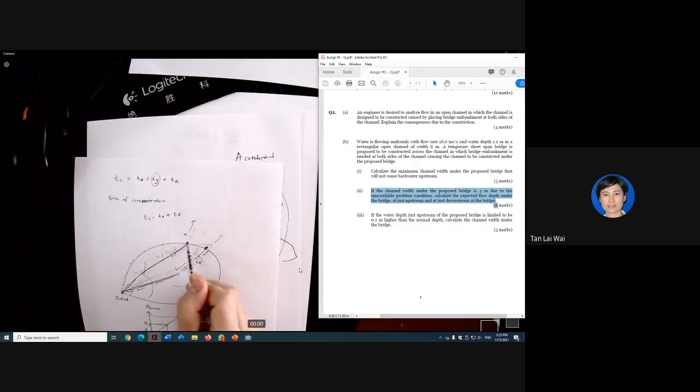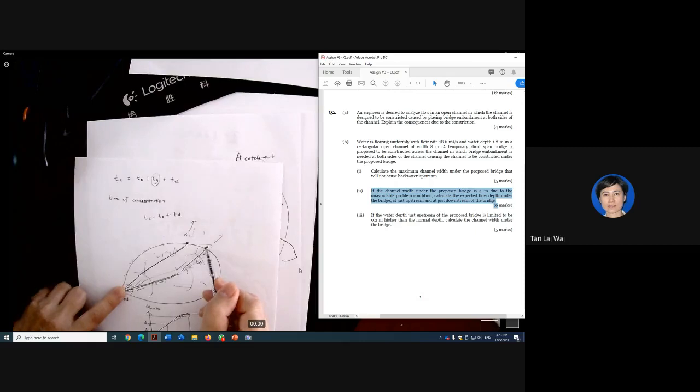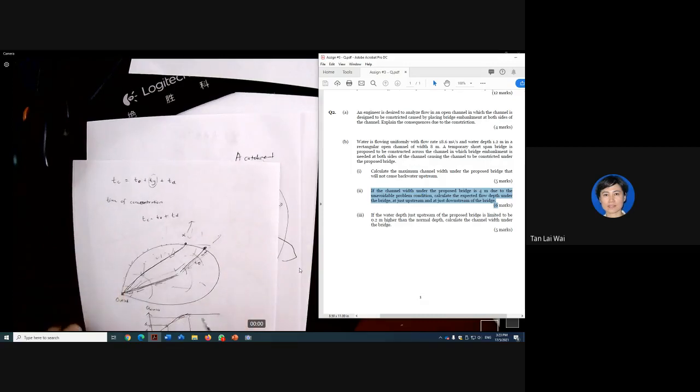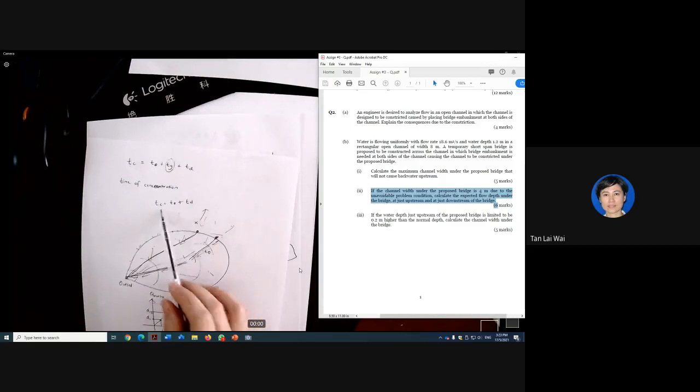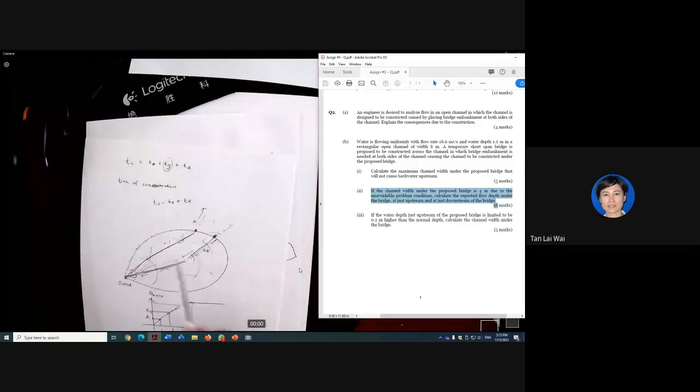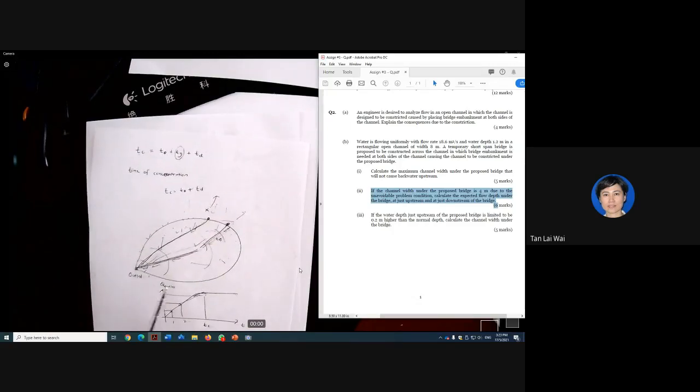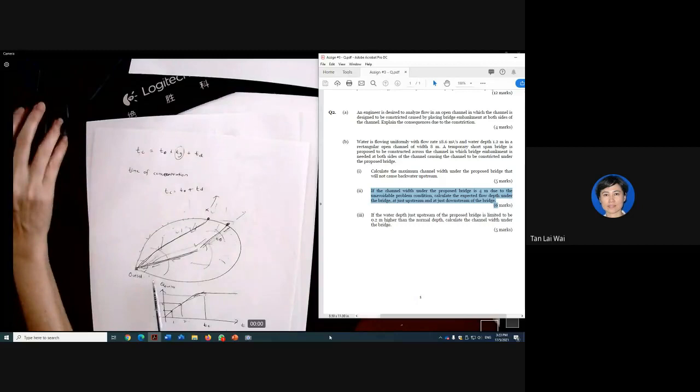When it's longer, you expect this runoff has already come out. So that's the point. Actually, the concept is the time needed for all the runoff at every point within the catchment to reach the outlet. So I hope you are clear with this explanation of the time of concentration.